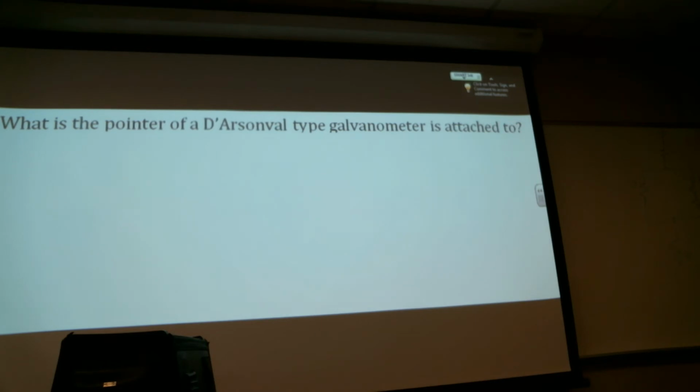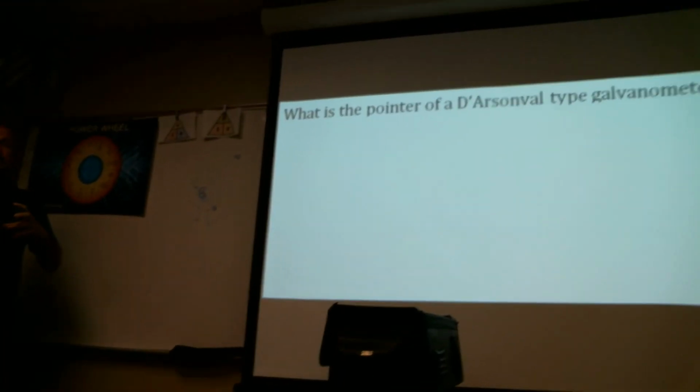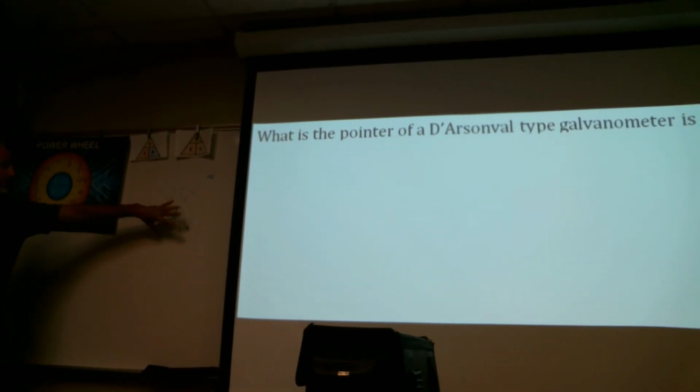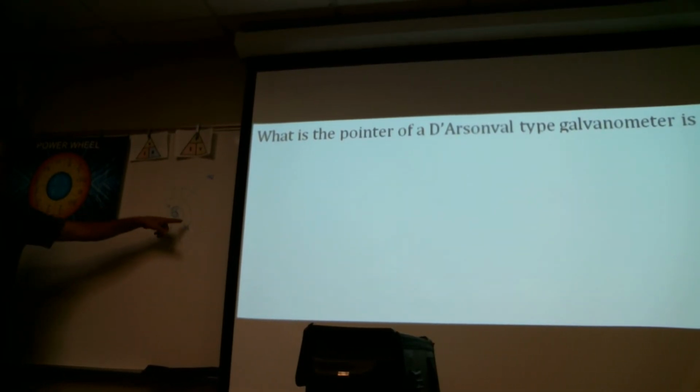So as you increase the voltage you're measuring, a very small amount of it is tapped off, and we'll talk about shunt resistors. A very small percentage goes to that electromagnetic coil. So the more we're reading, the greater the magnetic force in this little coil, and it wants to align with these permanent magnets out here.